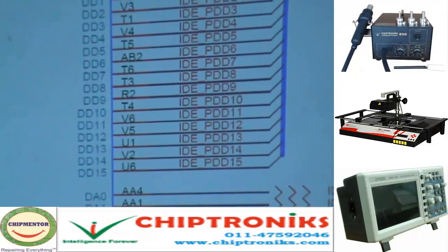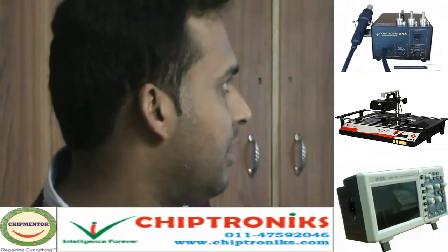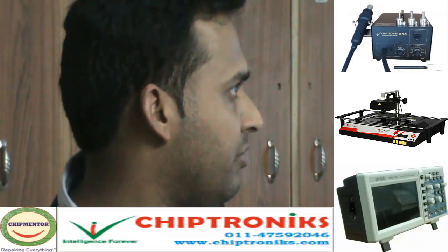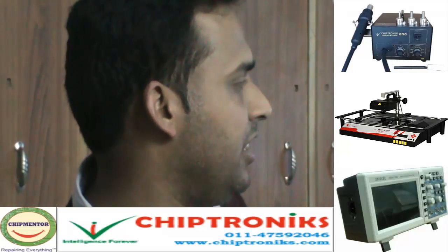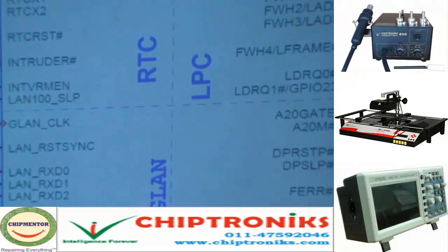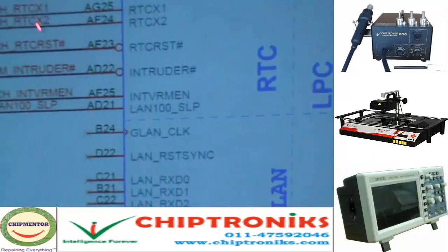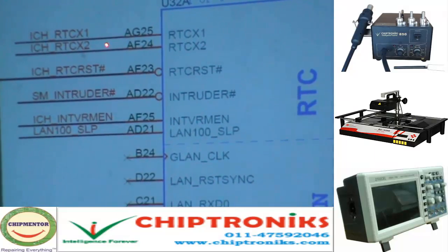This is ID connection. So we'll go back to page number 90. What important things have we covered? This is the RTC. Every testing starts with RTC. You have to remove the CMOS battery. This is ICH. It's fed through a crystal: ICH RTC X1, ICH RTC X2.